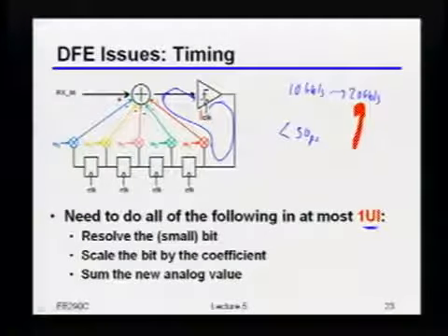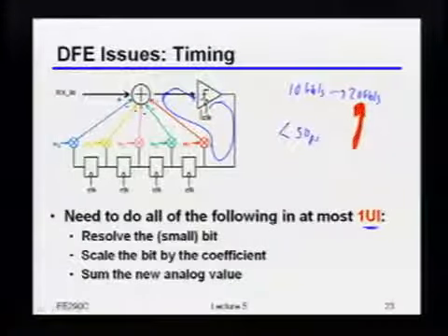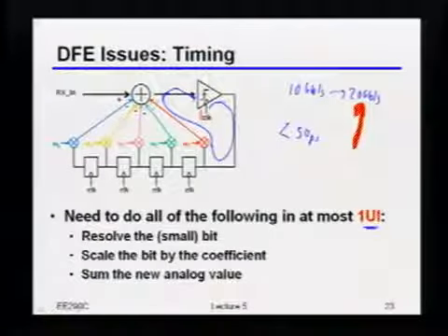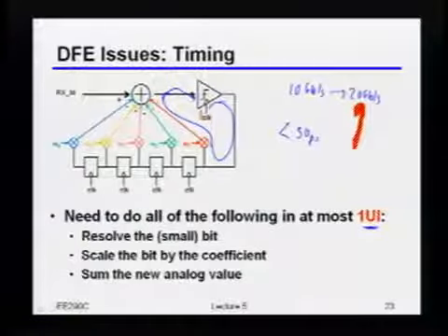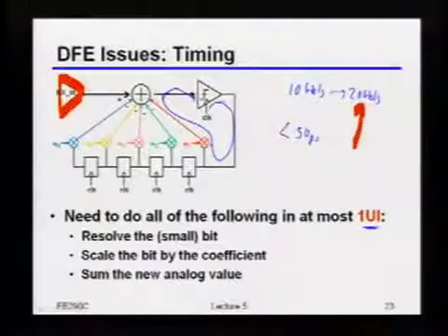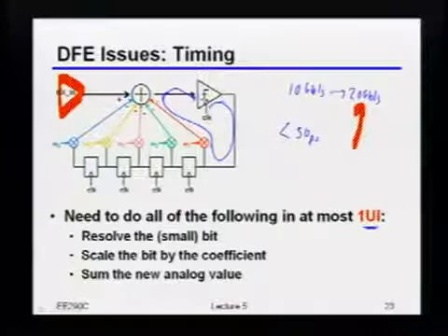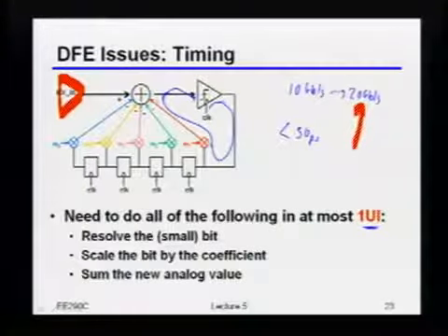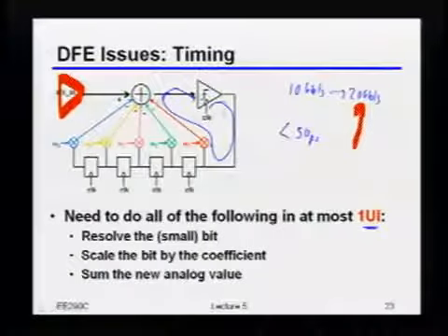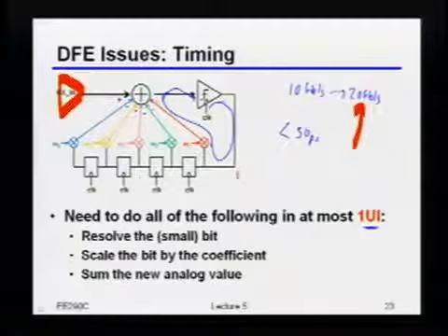As I said, and I am guilty of this, for this lecture I'm mostly focusing on the communication side of it. You're absolutely right that from the standpoint of how you build the circuits, it's not immediately obvious that the noise you've added from this transistor is all that much better than the noise that would have come from something else at the very front end. So you have to look carefully at where the noise in your system is really coming from. But you can imagine that if I have some linear equalizer or something with gain in front, then if you've done a good job with the chain, usually your noise will be dominated by the front end stages and not by this later stage here. It's not universally true, but generally speaking, that's the case.